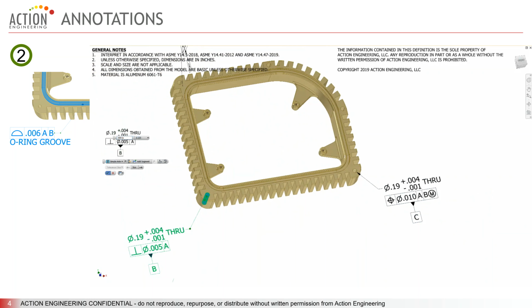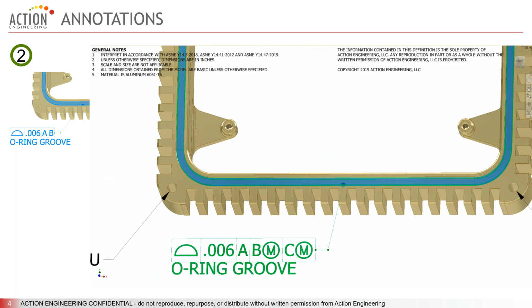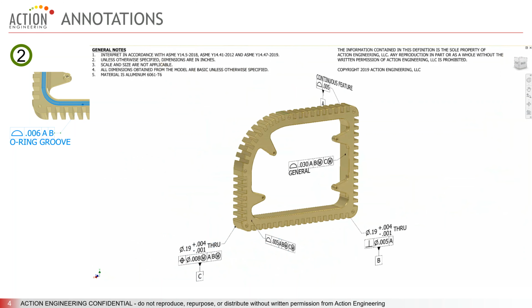geometry that they represent. The Digital Product Definition Data Practice Standards, ASME Y14.41, asks CAD vendors to not only ensure that manufacturing software programs know the relationship of the annotation to the geometry, but also to provide humans the ability to see the digital relationships on the screen. If we see it, we have increased confidence that the annotations were properly authored.